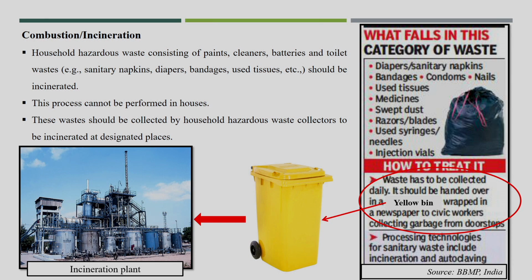Because the incineration process cannot work for a small quantity of waste, you will require almost 200 to 300 tons of waste every day, or more, for the incineration process. So, household level is not possible; we can go for a centralized incineration process.